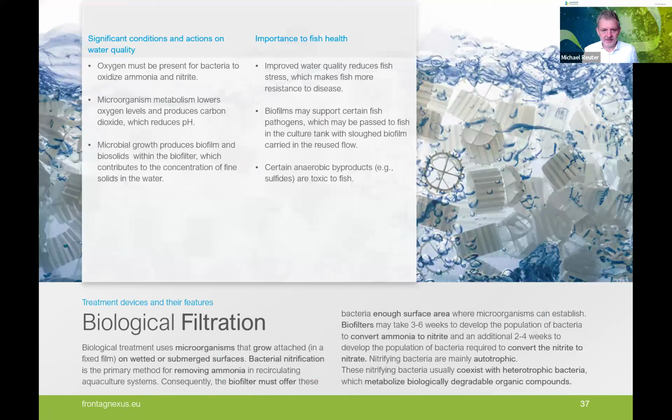Next step, as I said, will be the biological filtration. And for the biological filtration, it's very important that we already got out most of the solids, because otherwise the bacteria in the biological filter will have to deal also with the solids, which will make the processes in the biological filter much less efficient and also add a lot to the oxygen need of the biological filter. And that's one of the main aspects that we have to take care of in the biological filter.